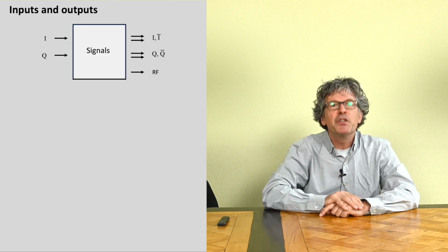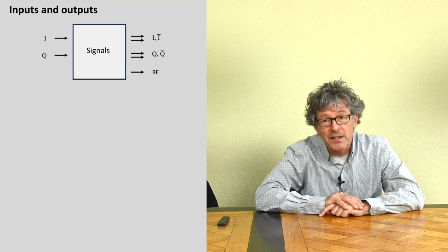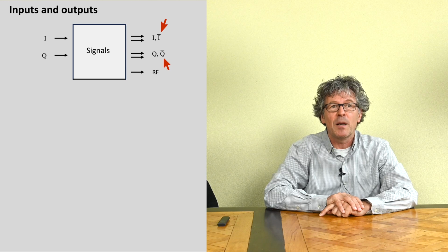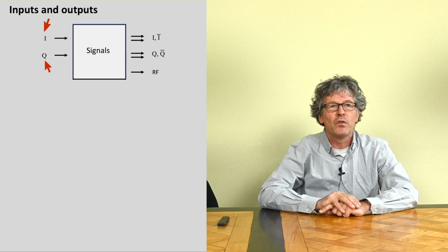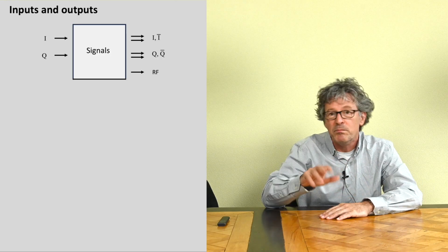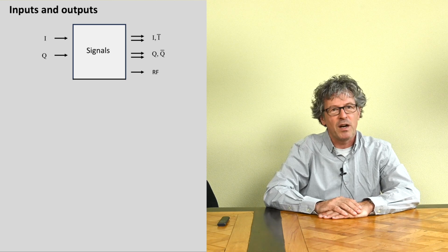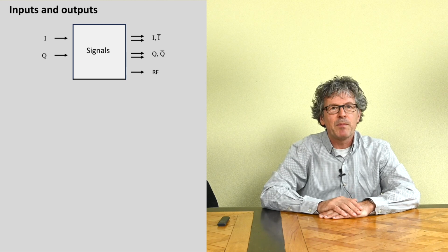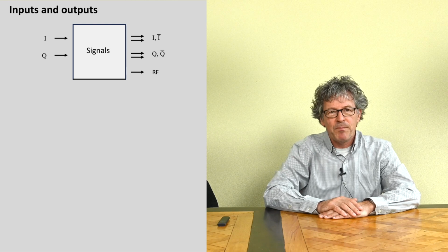But anyway, the I and the Q signals also come out of the device separately. There are also differentials, so you have a not-I and a not-Q coming out of the device. This is also standard. And you have I and Q inputs as standard on the front panel of the device, if your I and Q are coming from something else and you just want to modulate it, taking advantage of the wide modulation bandwidth of the device. The only thing here that I could complain a little bit about, and other people have complained, is the I and Q outputs, the differential outputs. They're on the back of the device.